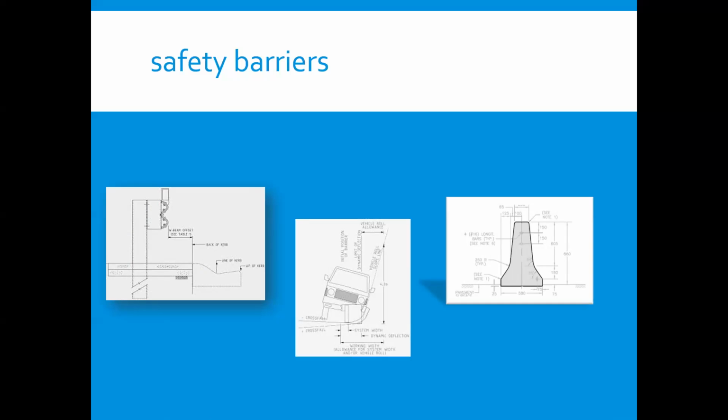Steel guardrail is perhaps the most common barrier, as shown on my sketch, and is used extensively in urban environments. The effectiveness of the guardrail is dependent on its length and offset from the main carriageway. The guardrail termination is also a concern, and standards are continually developing to improve end terminals.